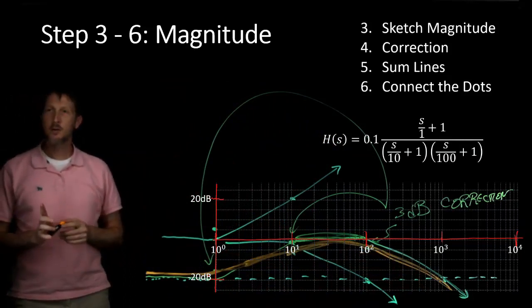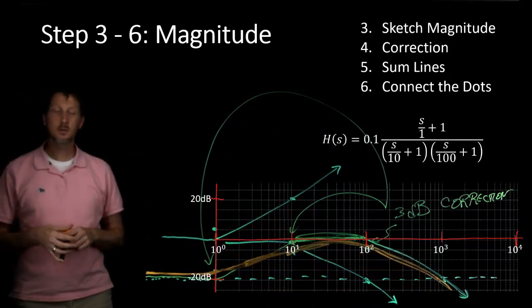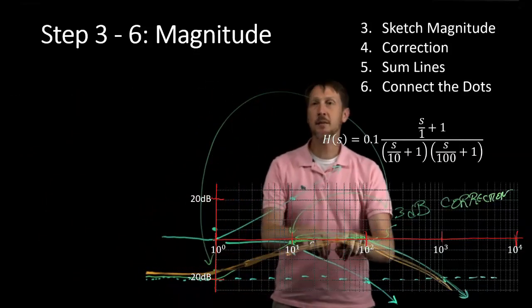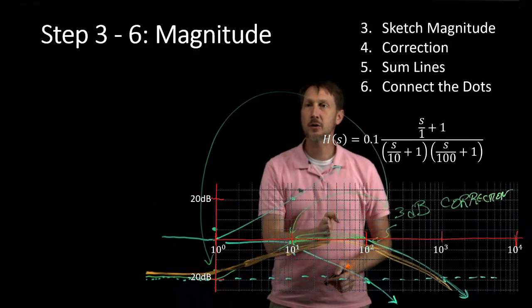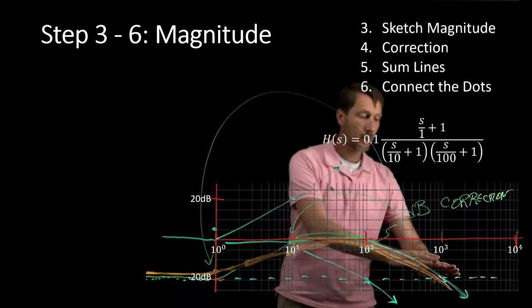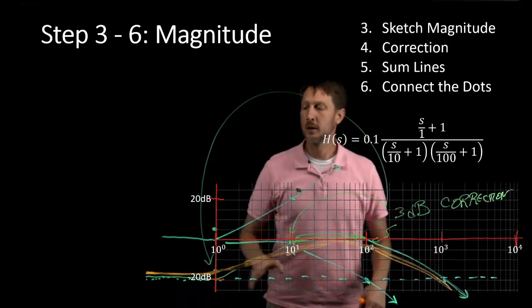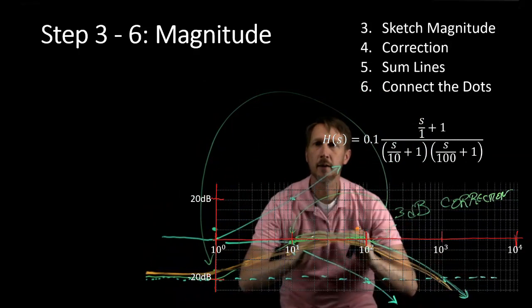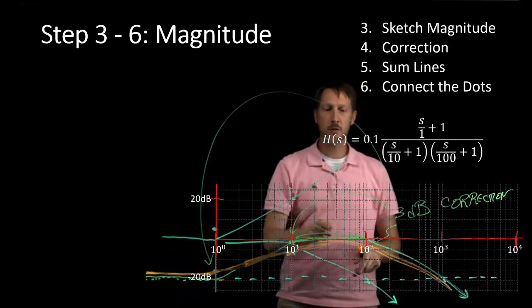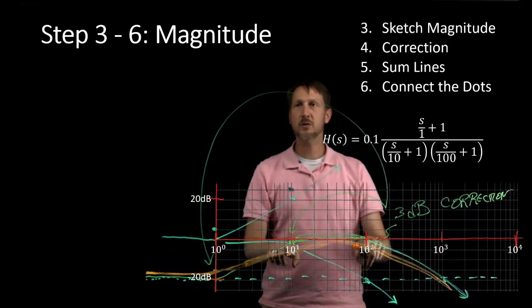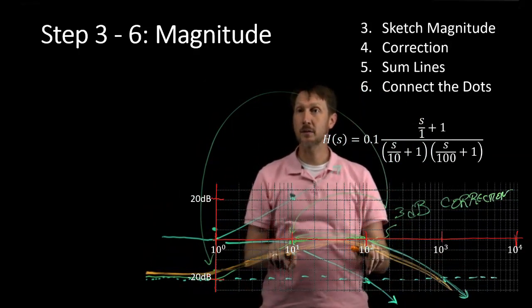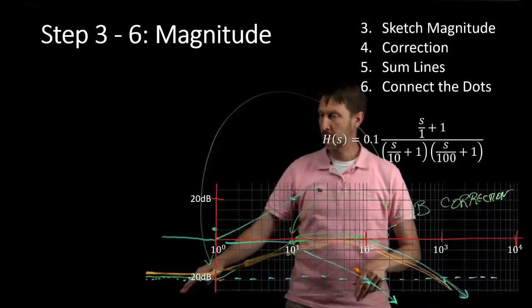You see that? You can tell that this is a bandpass filter. It is squashing the frequencies here, passing the frequencies here with a 0 dB gain, and then it's squashing them over here. So our filter shape comes up and comes back down, making this peak in the middle. Passband on either side of it, it's going to pass through these 3 dB correction points. That's our bandwidth. So we actually have exactly 1 decade of frequencies that we're passing. And then it continues off on both sides.